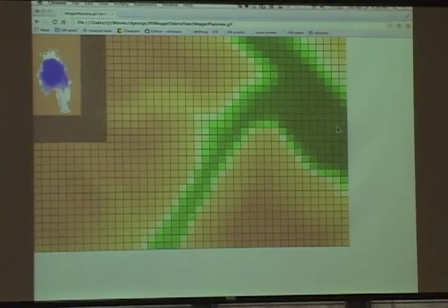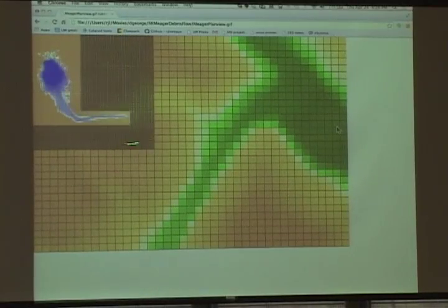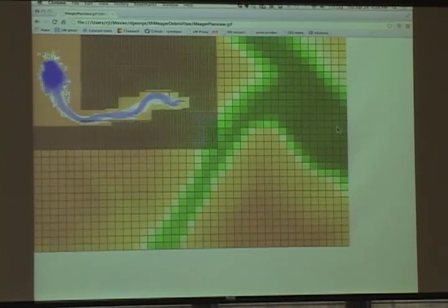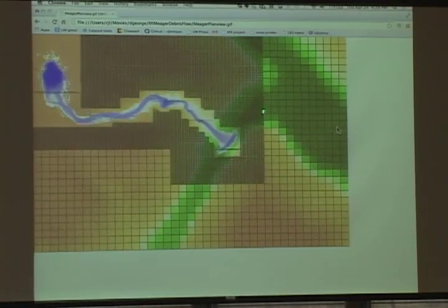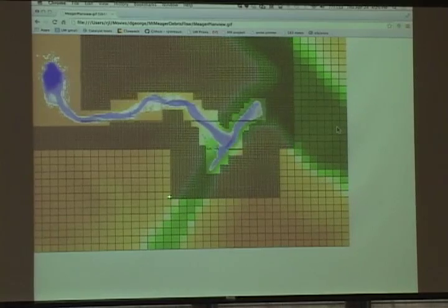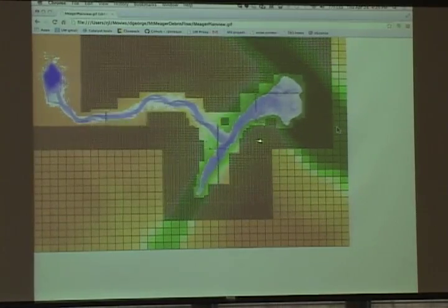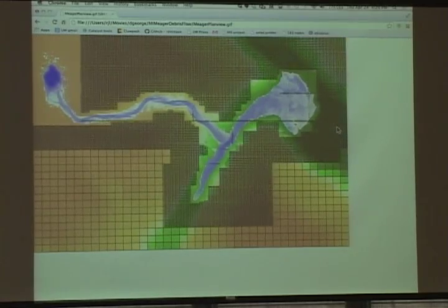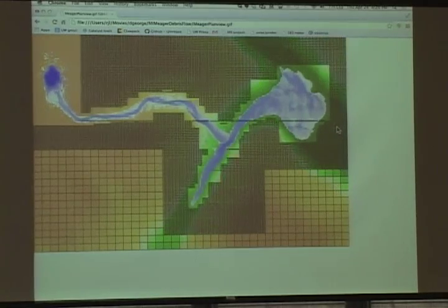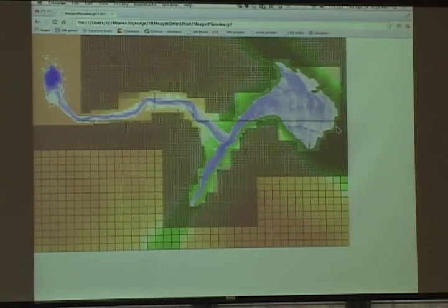It's a little easier to see what happens in the animation here. So here you can see the adaptive mesh refinement. We start with a very coarse grid where there's nothing happening. Then there's a finer grid that's refined by a factor of, maybe it's a factor of 6 or 8 in each direction. And then there's even finer grids where the grid lines aren't drawn that are actually able to resolve the flow as it moves.